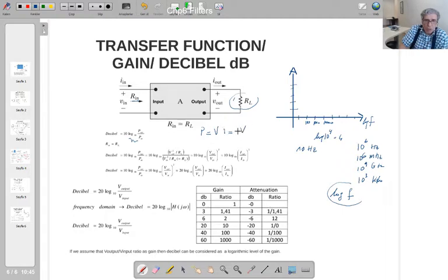If you write the current in terms of voltage, it is V over R, by the definition relation, so V squared over R, that's the power. So this is what is written here, and that is the power of the load. If Rin is equal to RL, the R's disappear, and what is left is Vout squared over Vin squared. So if you take the logarithm of it, you're going to end up with this, isn't it?